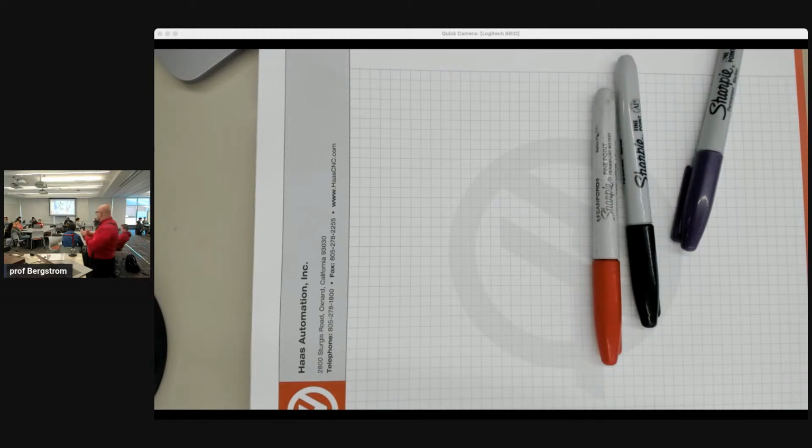All right, so that's the operator checklist, each tool as it's coming. After you've done it once, after you've run the part and it didn't crash, and now you're going to production mode of running that part, especially if you've got a part stop, so you're just putting every part in at the same location. Like we did the Y block, we had part stops. You didn't have to set the X and Y offsets. You're just putting the next part in. It's going to cut exactly the same way. You can go to that 100% rapid, press cycle start, walk away.